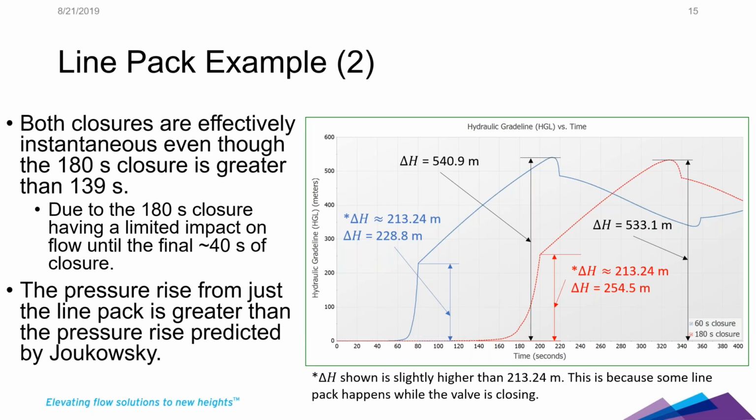We could have modeled this with an instant closure and basically seen the same thing. But all of this is highly system dependent. All of this is communication time dependent. All of this is valve dependent, your fluid. And then this is really going to depend on what happens upstream as well.